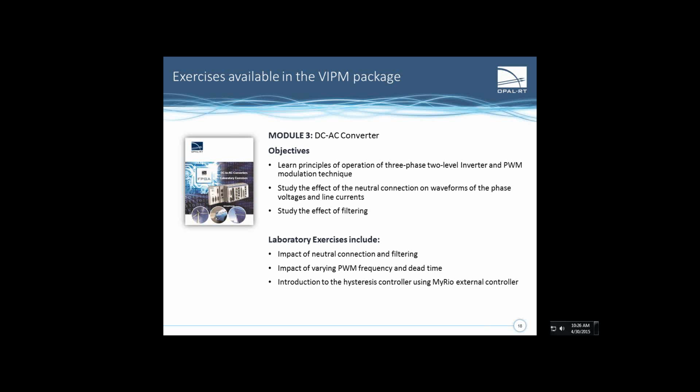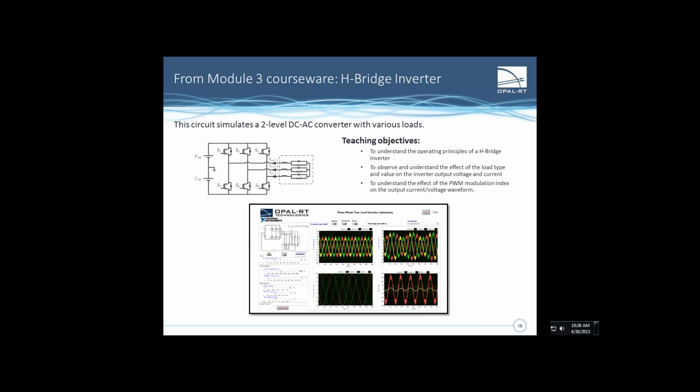The exercises allow the students to walk through the impact of the neutral point connection and filtering, varying the PWM frequency, the dead time, those sorts of things that actually go into implementing a real 3-phase inverter application. So they'll go through all of the different components that go into the design of that inverter. And you can see this is a screenshot of the front panel of that laboratory and also a block diagram of the inverter being simulated, the inverter and the load specifically.